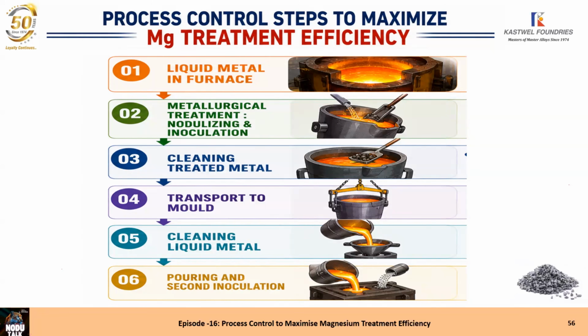Metallurgical treatment and nodularising inoculation. Cleaning the treated metal: first in the furnace, next in the treatment ladle, third before pouring the molds, cleaning the treated metal of the slag.